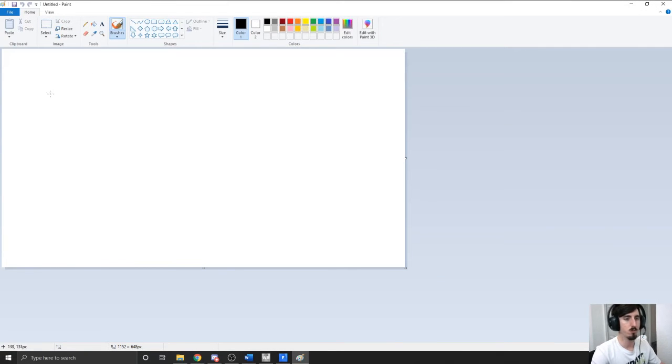Okay, so how I was talking about, our Reynolds number needs to be laminar. In this case, in our tube or a rectangular cross section, our Reynolds number to have a laminar flow needs to be less than 2000. To make sure we're not hitting any boundaries and getting weird outlier information, we're going to set our Reynolds number equal to 1000.